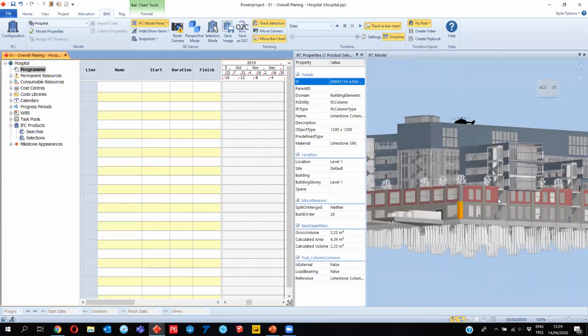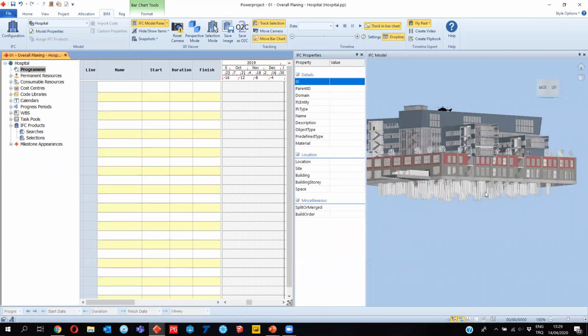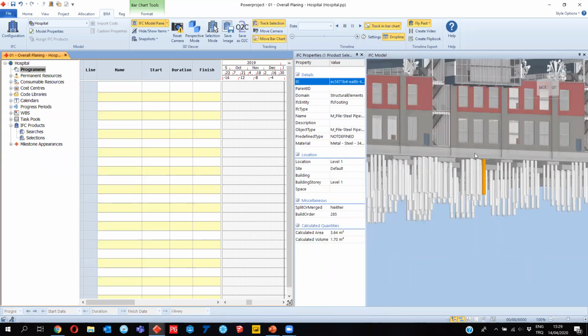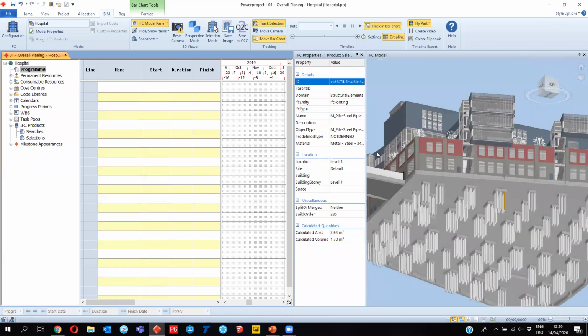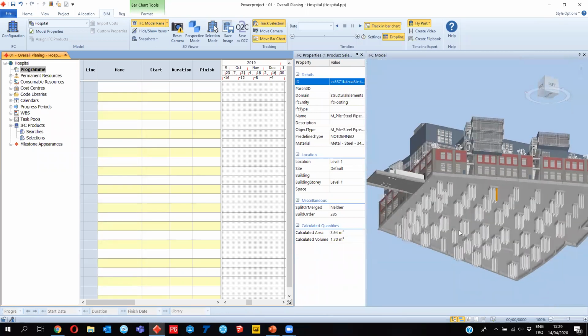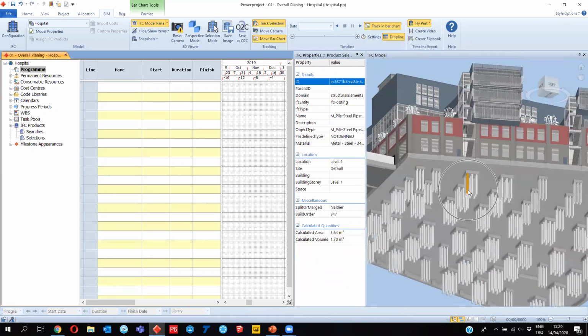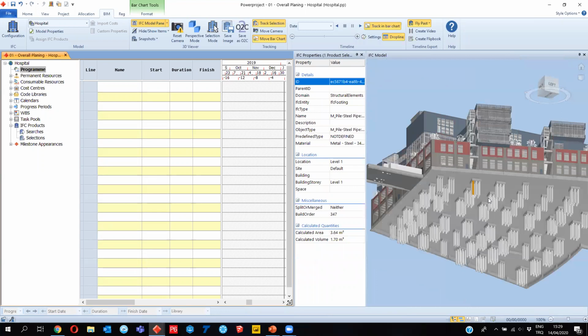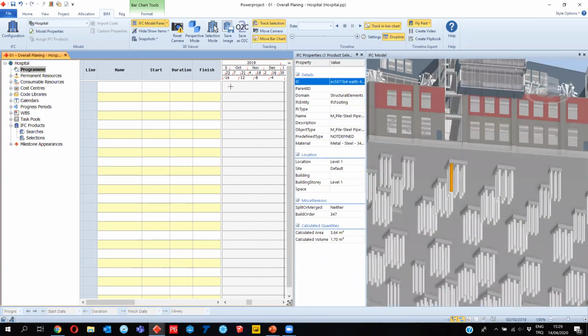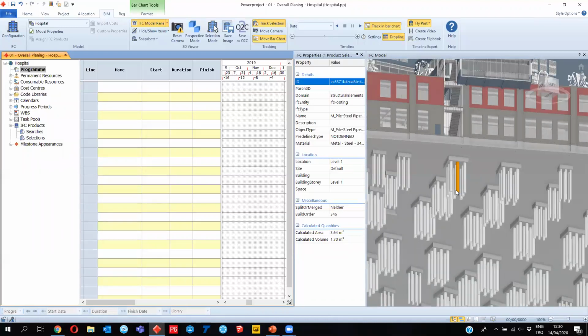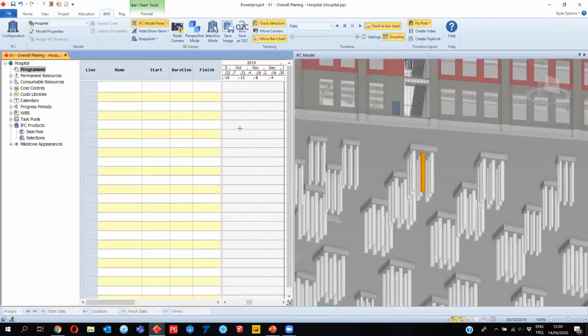Okay, so in order to create a first activity, we need to first start by creating our piles. You can also see that we do not have any related component based on excavation, but we can also create an excavation activity and then allocate the piles in another activity as piles, so we can have a more realistic schedule.